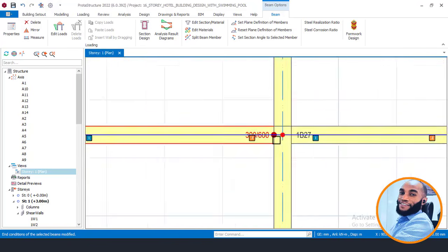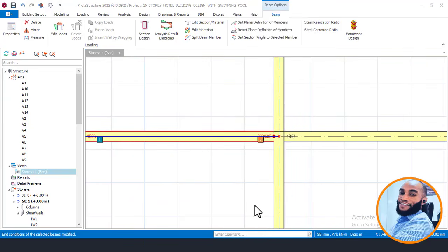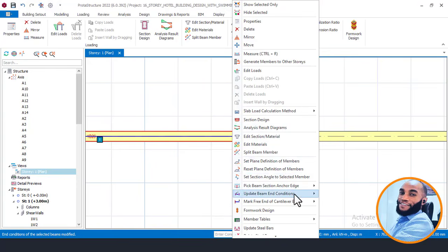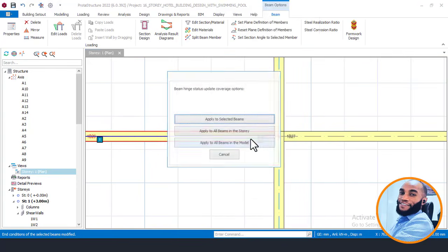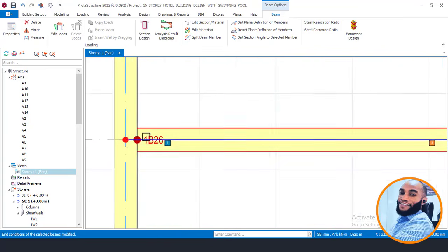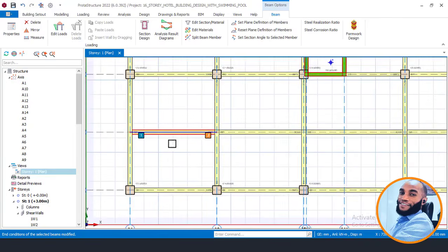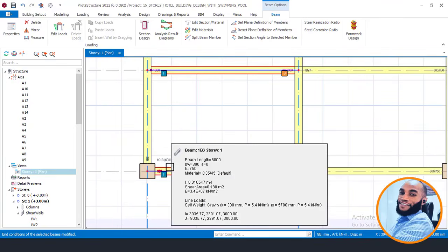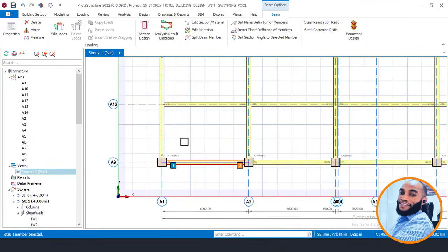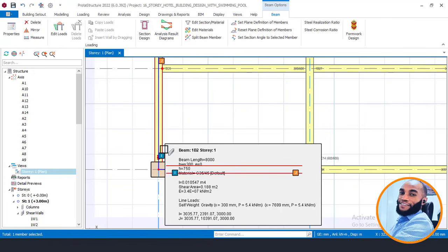Okay, no, not this end. Basically J I end. So I'll click here, right click here right now and then say apply to I end, and then say apply. It will now show a dot here. This dot here simply means hinge. So I'm trying to release the moment from this plate, because from the theory of design and analysis, every beam end is meant to be released, and that place should carry zero moment. So right now I will hinge every beam end.